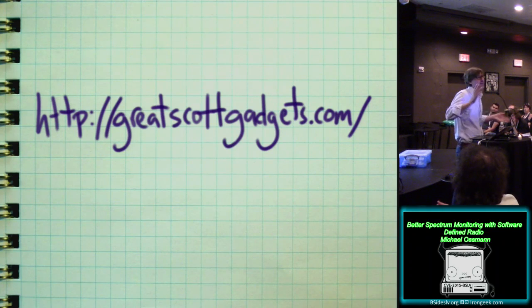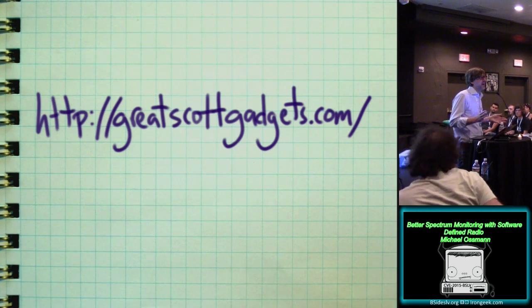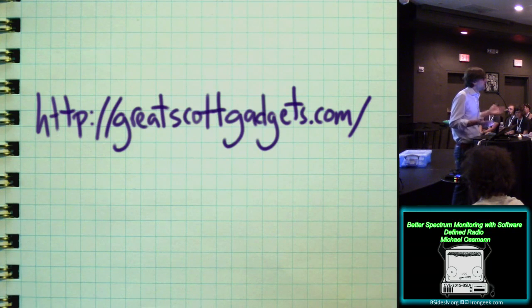There are horn antennas and various designs that are specifically designed to give you a good response over a very wide frequency range. But generally speaking, any antenna only has good performance over a limited frequency range, and every antenna is different. So if you have a set of antennas that are all used effectively, like if you're doing the array kind of stuff, an array of multiple receivers, and each one has its own antenna that's better for that particular frequency band, you might get much better performance.